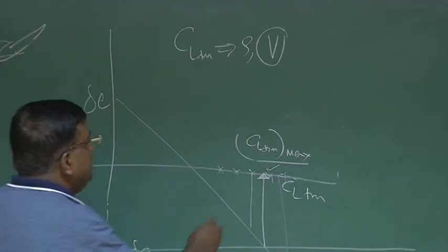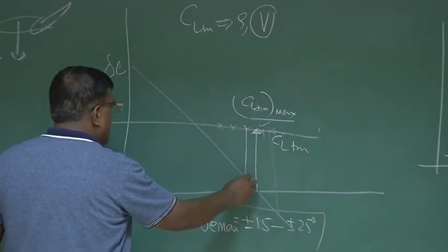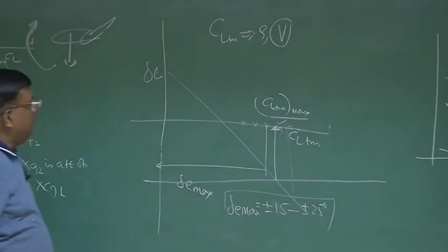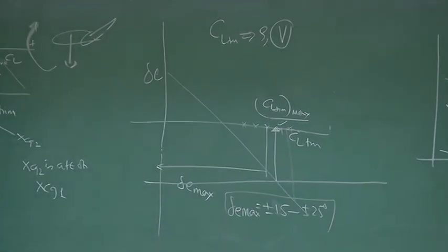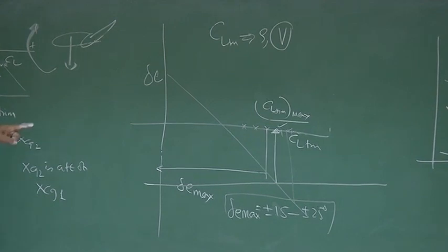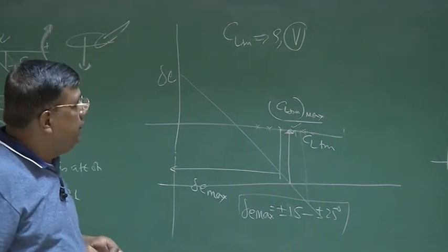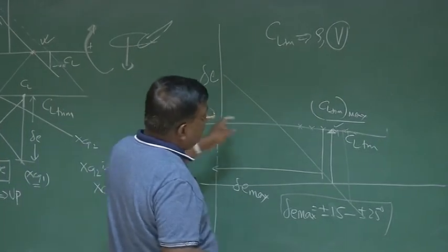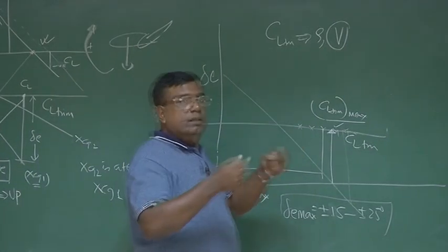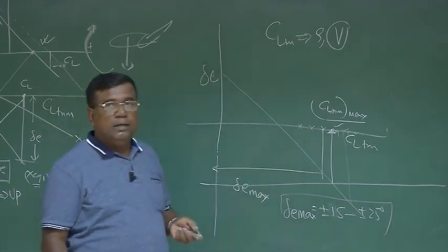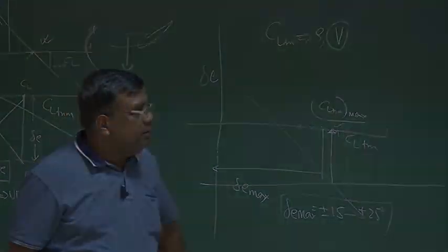So from this CL trim, he knows how much elevator up he has to maintain to go for that maximum CL trim. And he has every intermediate point and he understands. But the designer should ensure that the solutions are available, so that the pilot, by iteration, can find that solution. Okay? Thank you very much.